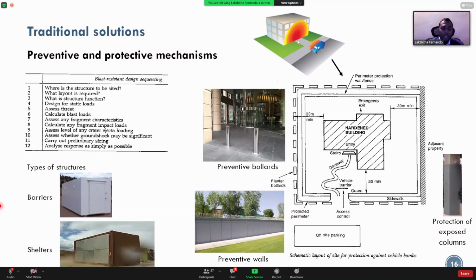And to this end, we have this idea of vented structures in designing barriers. It's sort of a more advanced version of the ventilation that we provide, to make sure that the gases that can cause explosions, as well as the excessive pressure when there's an explosion, can move out of the structure quite easily. We are creating a free pathway for it to move out. So that is if our structure is a barrier.